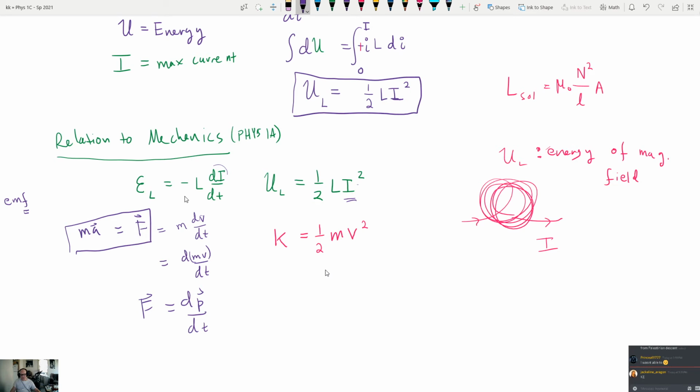So one way to talk about that is saying force is equal to mass times acceleration. The charges are already moving in one direction. It's going to take a force to stop them from moving, and that's going to cause them to decelerate. Or you can think about it as you've got all these electrons moving. They carry energy, and that energy can't just disappear. It has to go somewhere. So however you want to think about it, for me, this makes understanding what inductors do a lot simpler.